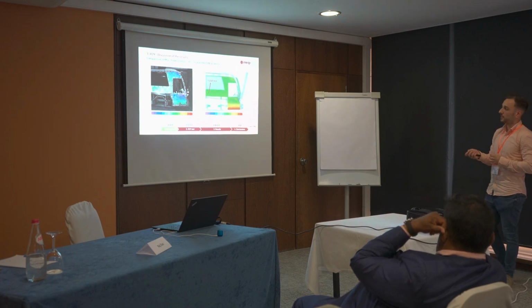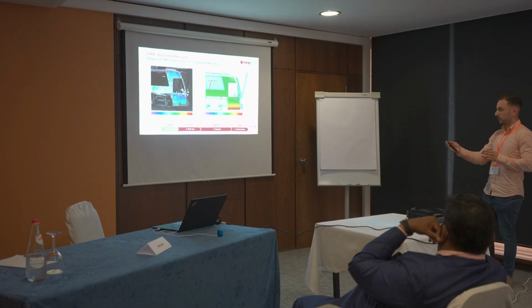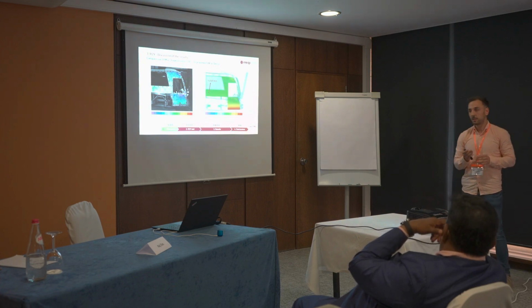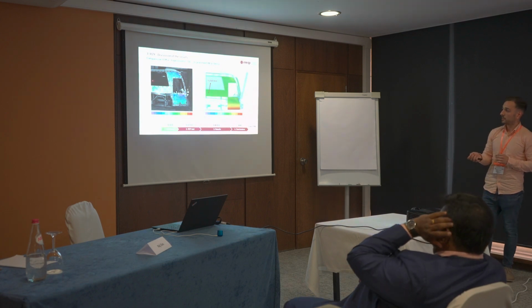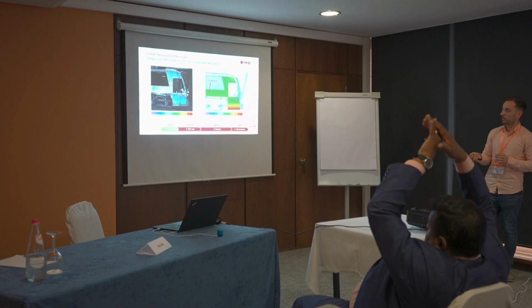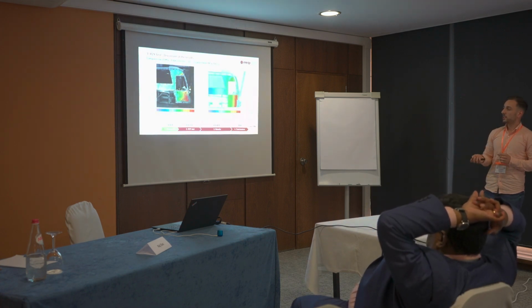If we look at this node, the displacement of this node, it retracts almost 50 millimeters, and 50 millimeters in the experimental test corresponds to the green color. It's almost there. On the vertical side, where the crushing area has lower influence, the contour field has a better correlation.